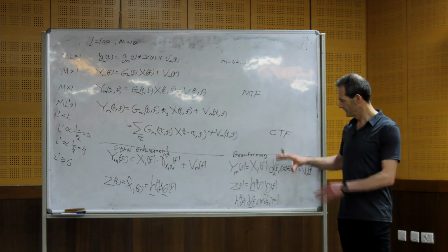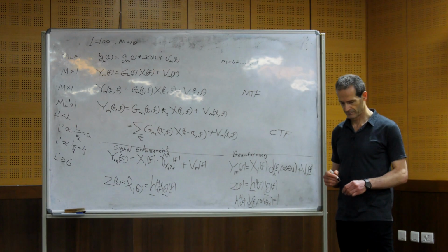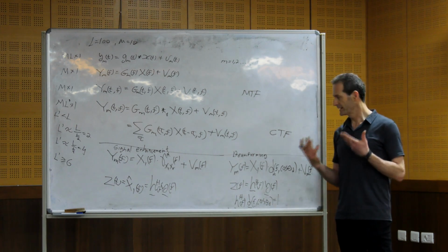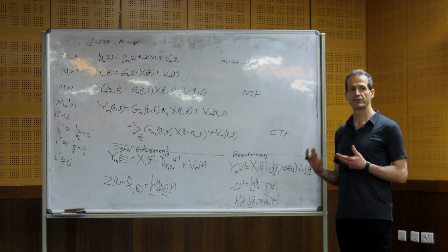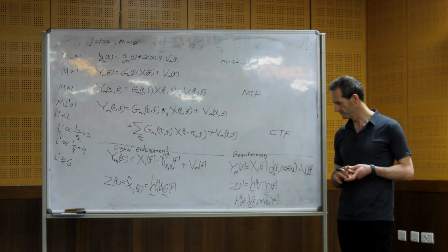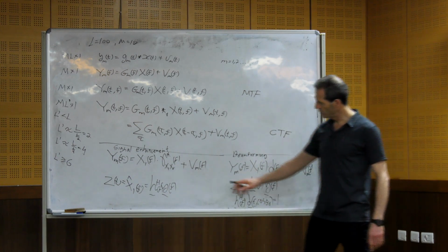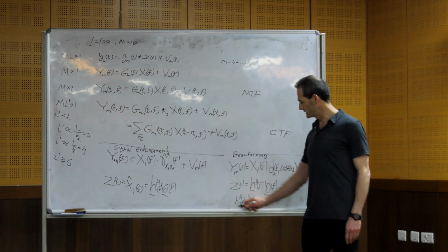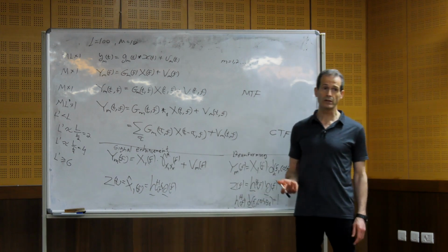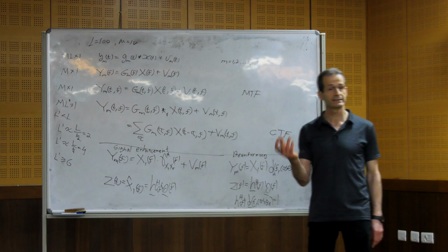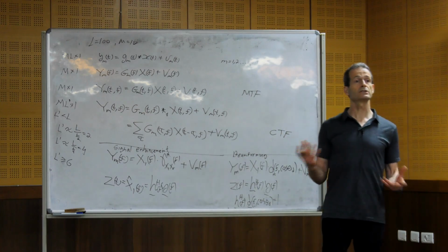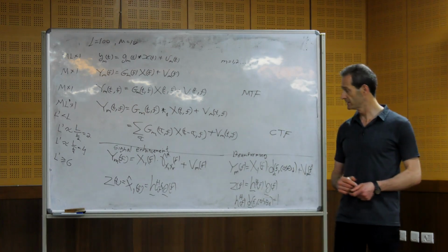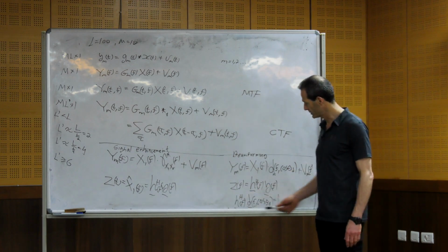This is beamforming. Okay, but you see, it's very similar. So the methods also are similar. Here, we don't necessarily use this constraint unless we want to work with MVDR or LCMV with distortionless responses. So we add something similar to that.